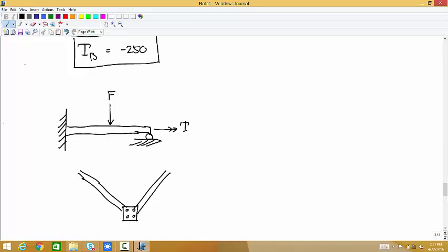But since the forces that this joint provides to the members dominate the couples that it's capable of providing, people, when they do this mathematically, simplify this by pretending that it's really this. And you can get good results that way. But if those couples were providing important restrictions on the motion, then you'd have to use statically indeterminate approaches.